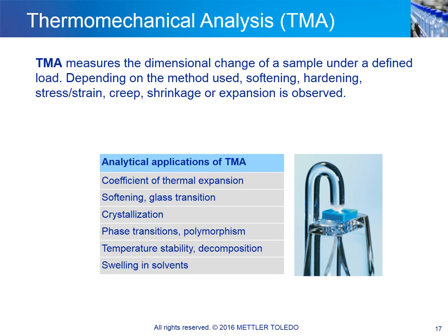The table summarizes the analytical applications of TMA in the field of quality control. One of the applications is the determination of the expansion behavior and the coefficient of thermal expansion, or CTE. TMA is also an excellent technique for determining glass transition temperatures, for studying softening behavior, polymorphism, and swelling behavior in different solvents. The picture on the right shows a typical experimental setup of a ballpoint probe in contact with a